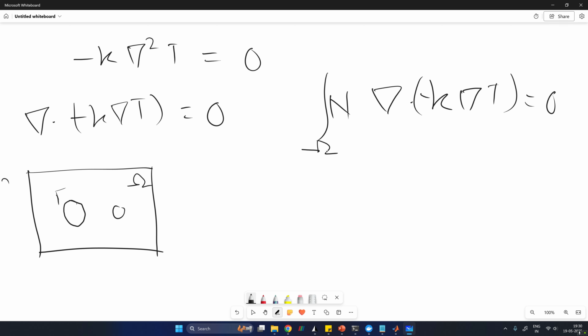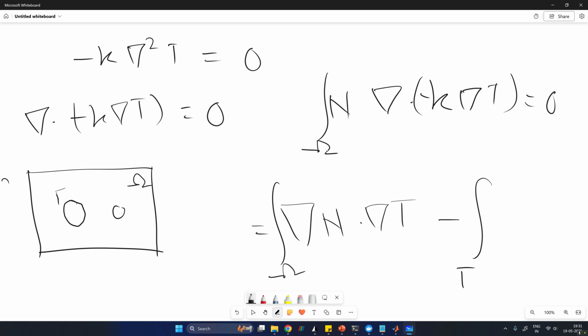So when we integrate by parts, we'll just get this expression. So the minus sign will just get cancelled, and so this is the problem which we solve inside the domain, for which we derive our stiffness matrix, and then this is your boundary integral, right? So this is basically just like your flux, right? And this n guy is basically just your shape function on this boundary.